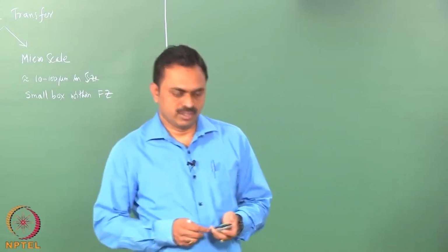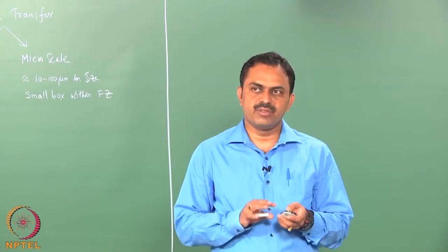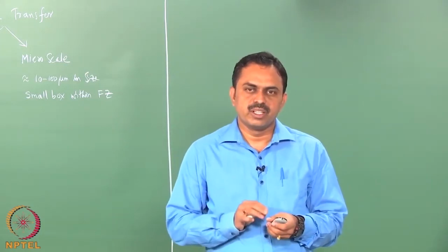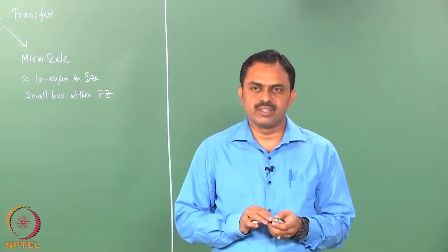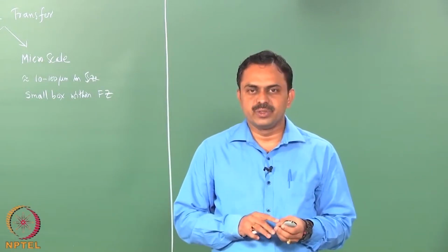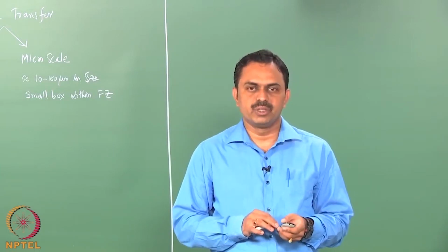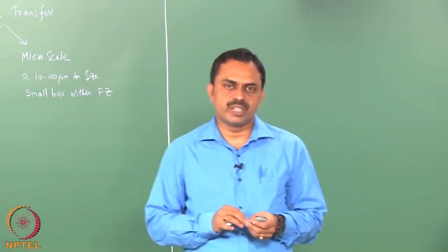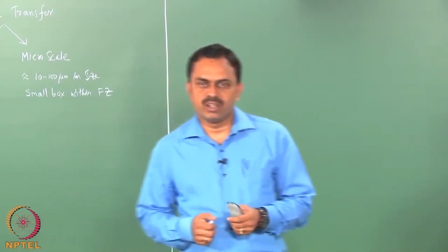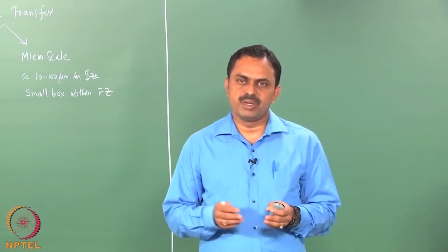So, welcome to the lesson on solute transfer modeling. In this lesson, which will be in several small parts, we will be discussing the modeling of the solute transfer, which is basically the composition distribution, and this has to be done at two different length scales, unlike the thermal or the fluid flow. The reason being the solute transfer is governed by the diffusion coefficient, which is very small compared to, let us say, thermal diffusivity or momentum diffusivity.